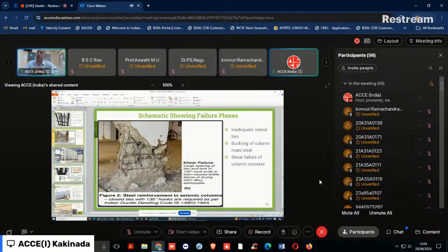In this mode 1 failure, the loading is in the form of axial forces. These axial forces come from the gravity loading. In addition to that, the lateral forces, acting as a distribution of the interstory shear of the base shear in proportion to the lateral stiffness, will subject the frame to a lateral deformation that will induce the push-pull action of the columns.